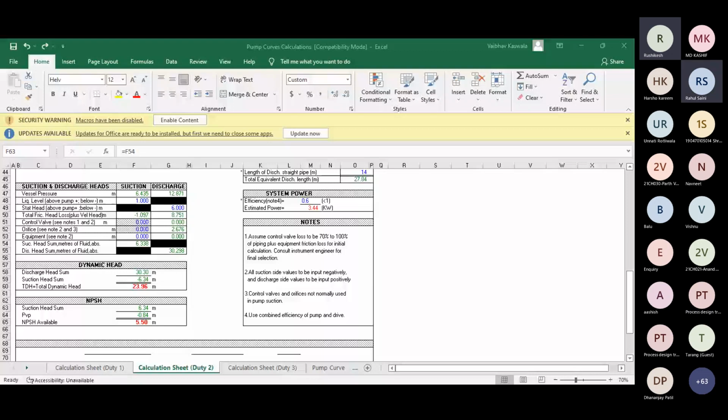My doubt was, is the pump size somewhere related to the discharge line size as well or not? It is not independent from that. Pump sizing will totally depend on the discharge line. Because if your discharge line is smaller, what does that mean? See your requirement for a plant, suppose 10 meter cube per hour is the flow rate you want in the plant.